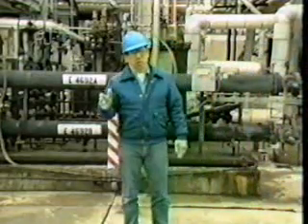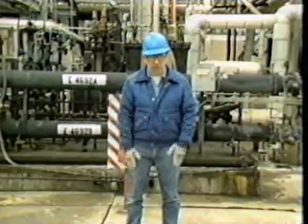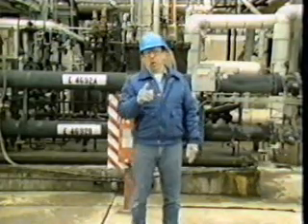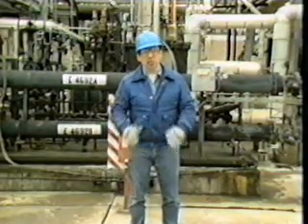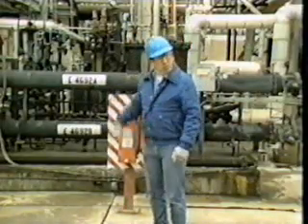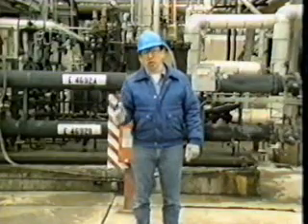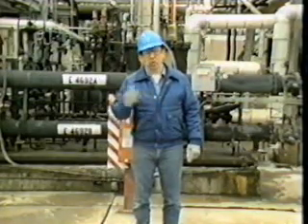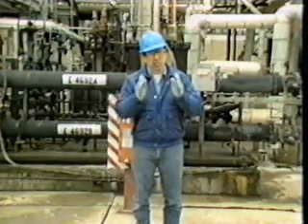Almost any large machine needs some type of lubrication, and a centrifugal compressor is no exception. Without the proper lubrication, frictional heat could build up to a dangerous level, possibly damaging the compressor. That's why lubrication systems are so important. Most centrifugal compressors use external lube oil circulation systems to lubricate and cool all bearings and gears in the compressor and accessory drivers.